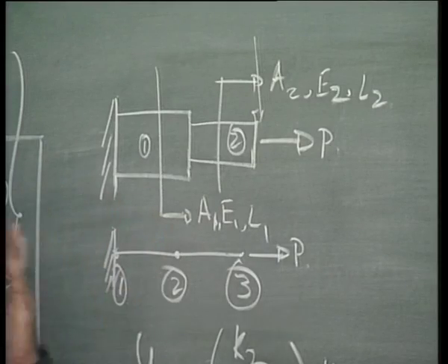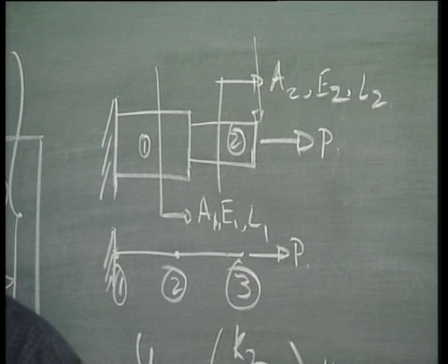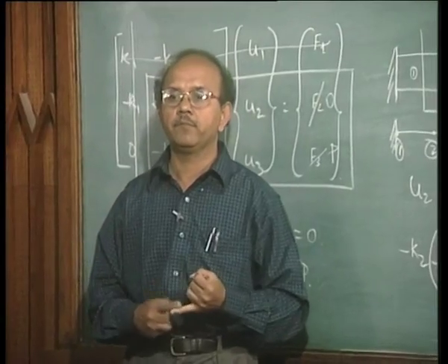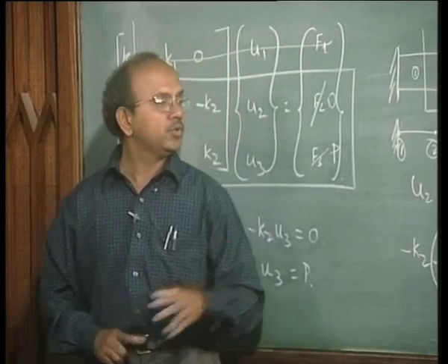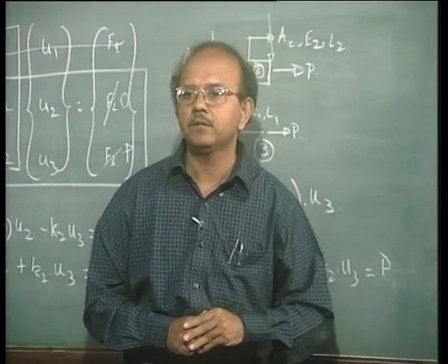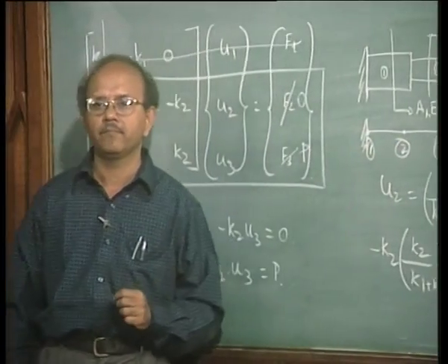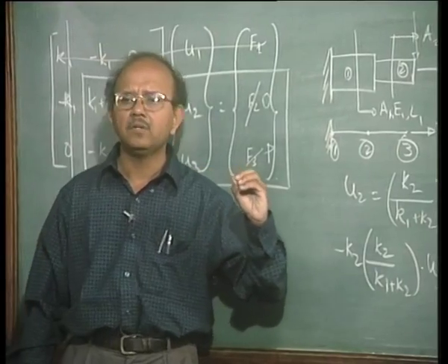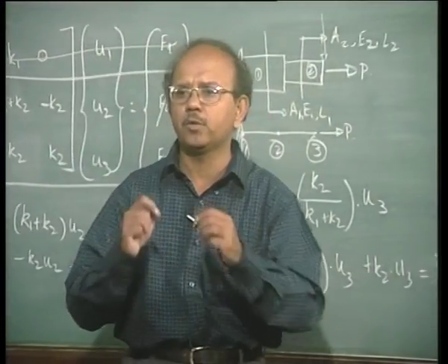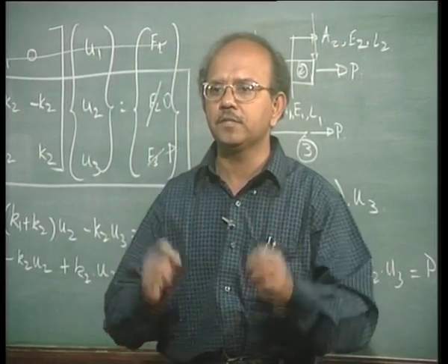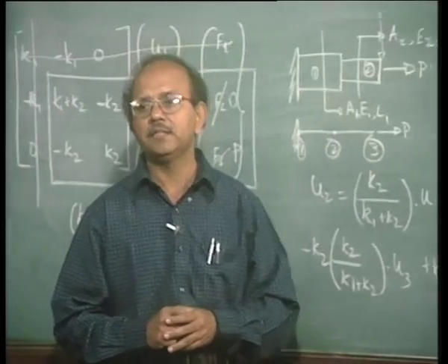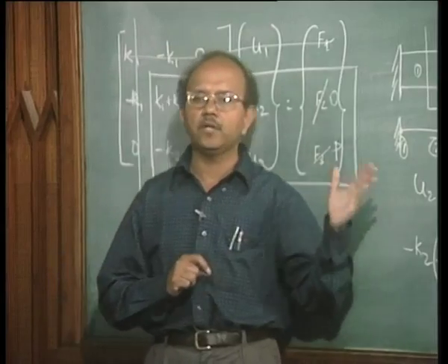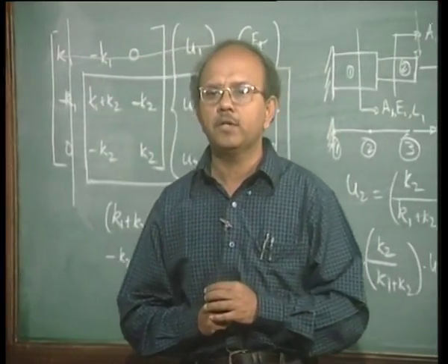Knowing how the material or the geometry is going to behave under a combination of the geometry as well as loading, you said, let us choose bar element, first thing. So, after choosing the element, what did you do? You discretized it. You divided it into two elements. Why did you do it? Before you did this, you immediately had an idea of what is stiffness of a bar. That is what we did. What is the stiffness of a bar? Then you realized that there is going to be a term, say A1 E1 by L1, which we called as K1, and A2 E2 by L2.